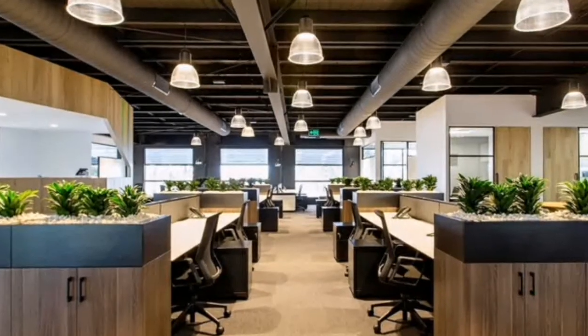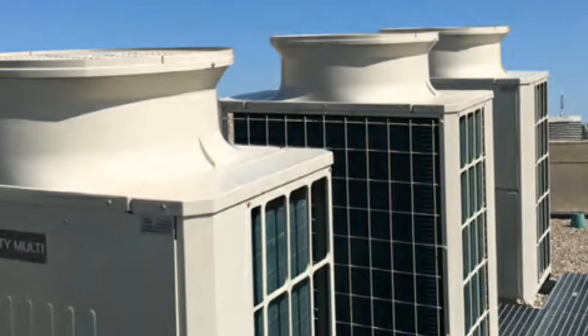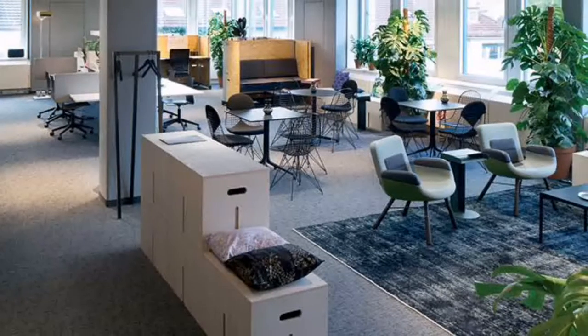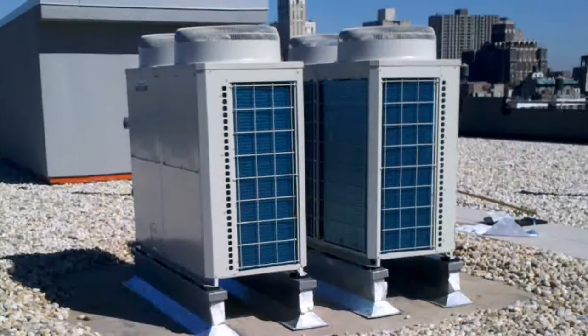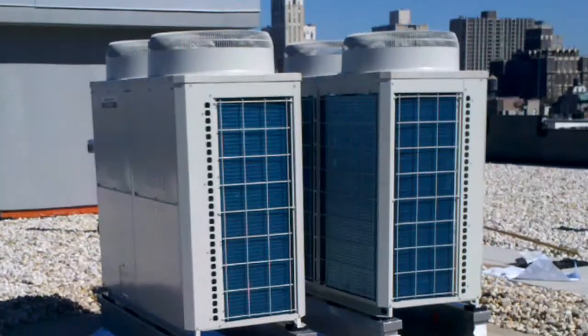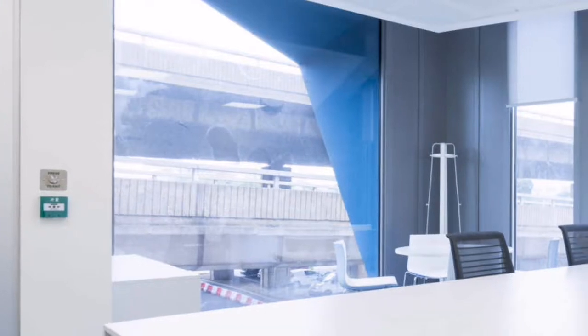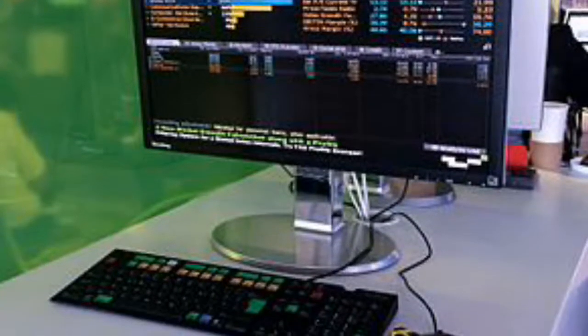If excessive heat is being generated within the building overall, the system removes it to the outdoors using air conditioning technology. If not enough heat is being generated internally within the building, the system injects heat from the outdoors using heat pump technology. Each room has a temperature sensor, and control is maintained through a centrally operated computer program.